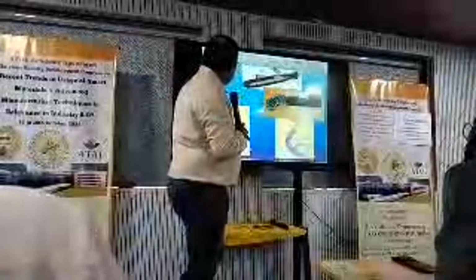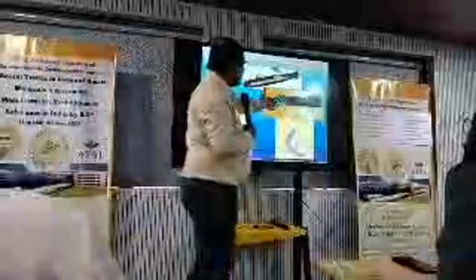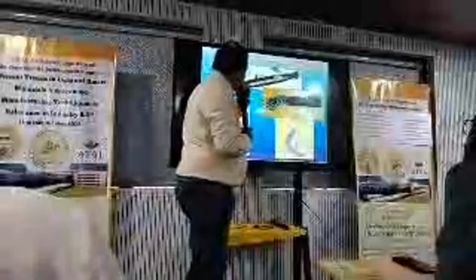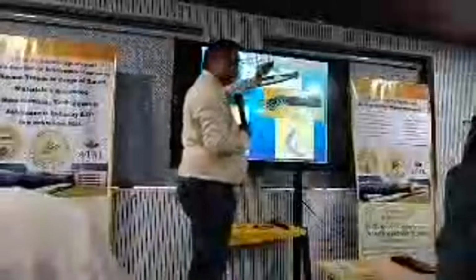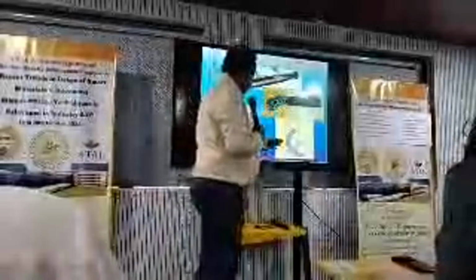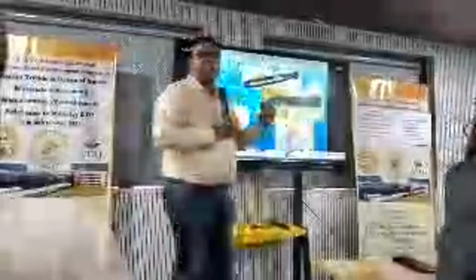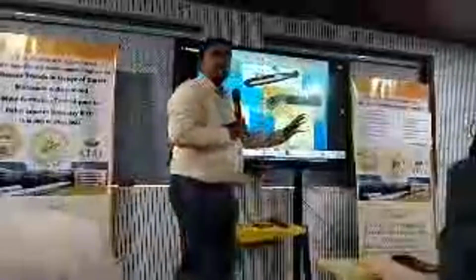And this is the acoustic tile, one of the typical submarine outer hull. The rubber material we have to select such that it will be bonded on the outer surface of the submarine. The main aim is it won't allow the inside noise to go outside, because if it allows, the enemy will detect it. And also the outer noise which is coming towards the submarine, it will absorb.